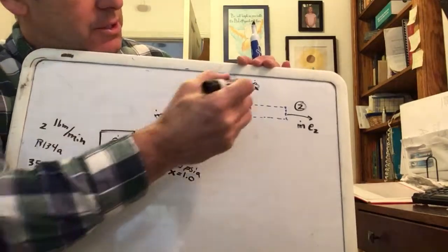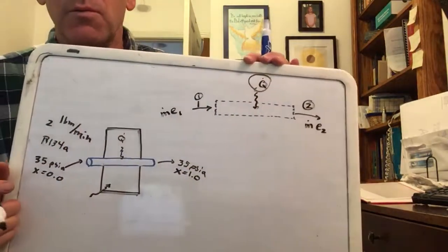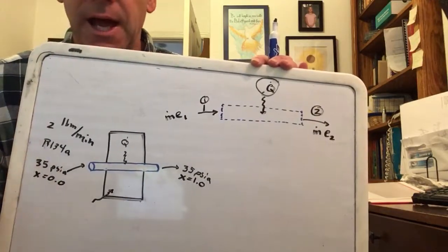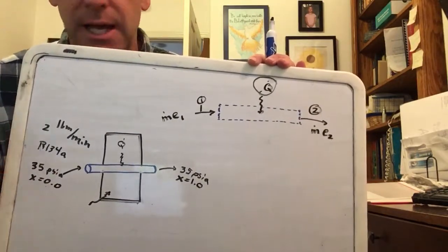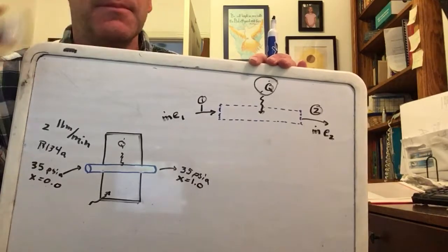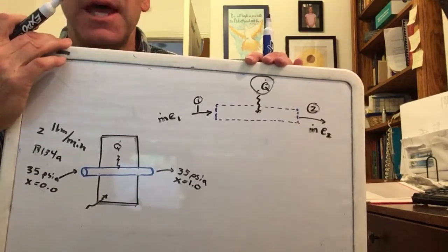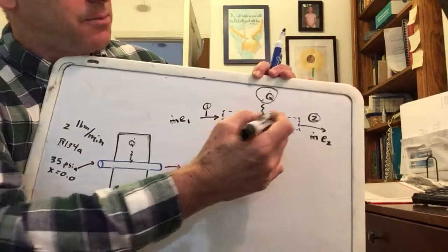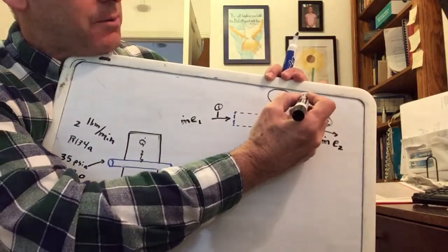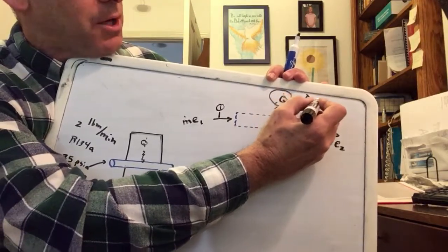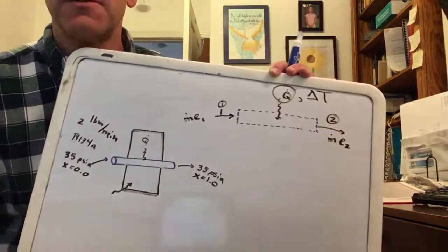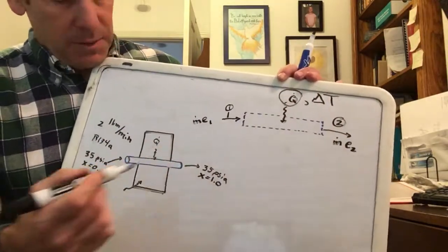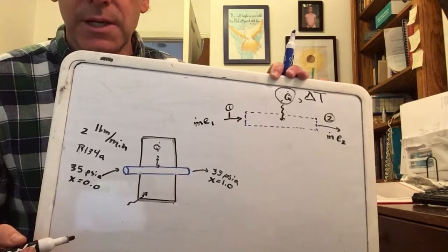Okay, so then the question is, can we solve for Q dot there? Well, that's easy enough. Just a couple quick notes. No work. We don't have any fans or compressors or turbines or anything like that going in the system. And Q dot would stand for the net heat transfer in. You'll see how the numbers work. Besides figuring out what's going on with Q dot, we'd also like to get, what's the refrigerant delta T as it goes through there? Let's just take a look at the numbers really quickly and get T1 and T2.